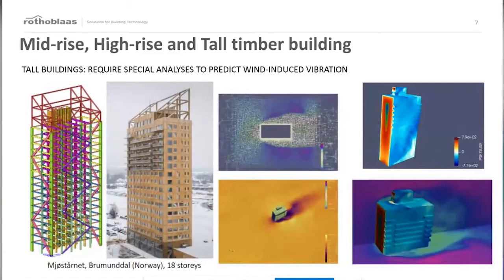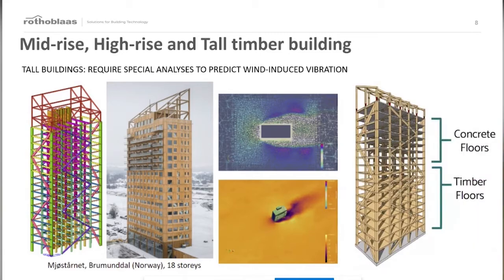Similarly, for this type of structure, special analyses are necessary. For example, the wind-induced vibration analysis allows us to define the effect of special environmental action on the structure and allows us to make some special design choices, such as the realization of some concrete floors in the upper levels of the building.